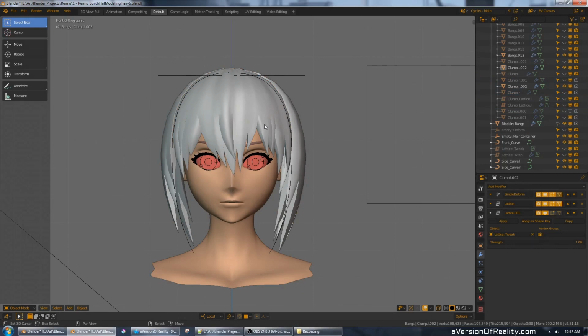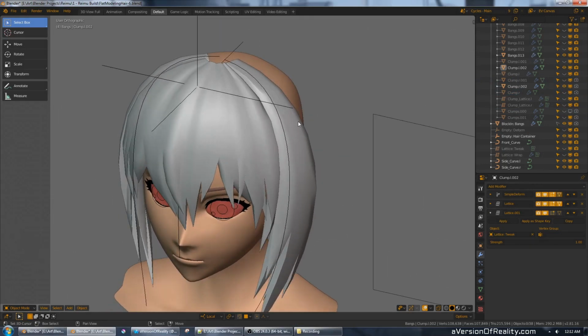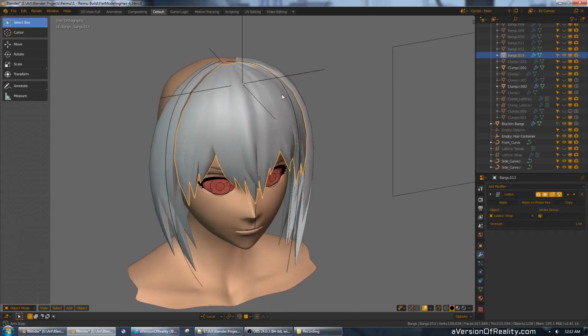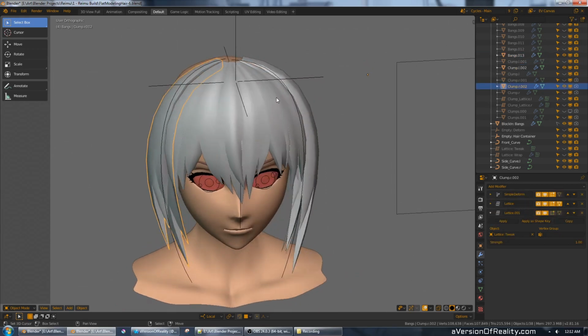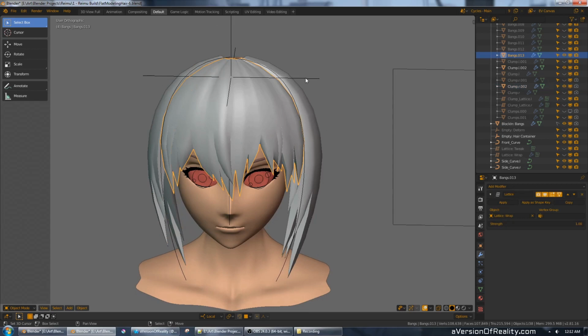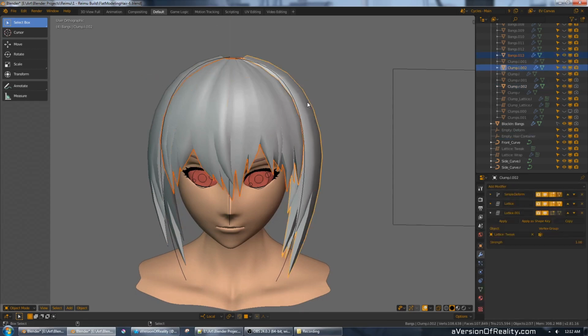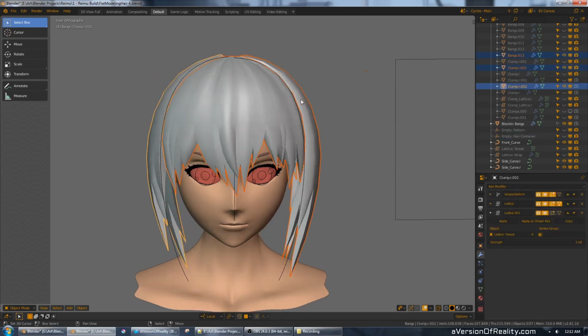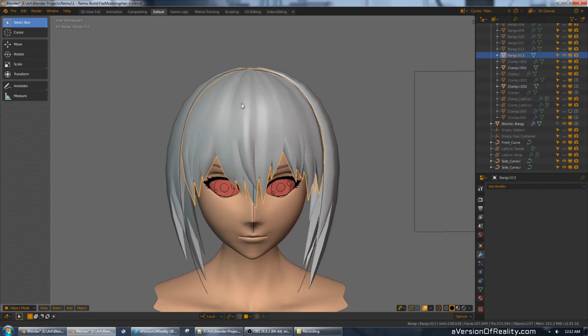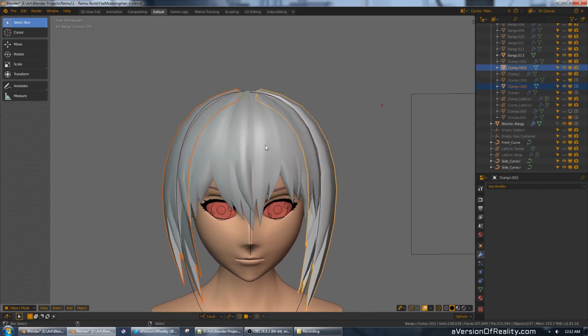But just a couple things left to do. First, we need to merge these pieces together and bridge them. You may have noticed I removed the subsurf, and that's because rather than manually go through and apply modifiers on all of them, I'm just going to do a Control-A, Visual Geometry to Mesh. That just applies all of their modifiers immediately. And I can join them together.